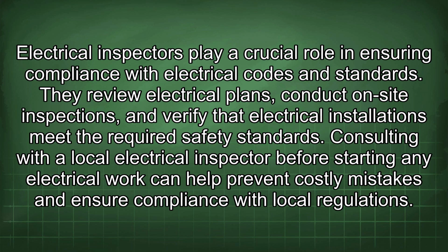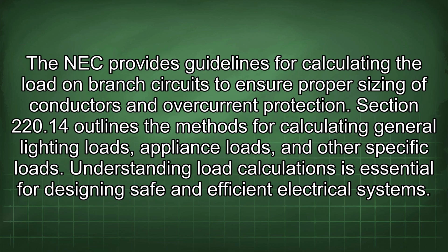The NEC provides guidelines for calculating the load on branch circuits to ensure proper sizing of conductors and overcurrent protection. Section 220.14 outlines the methods for calculating general lighting loads, appliance loads, and other specific loads. Understanding load calculations is essential for designing safe and efficient electrical systems.